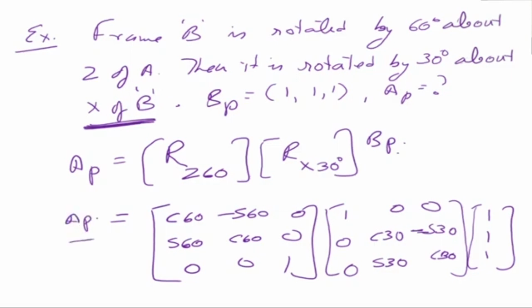So what we noted here is that we have not pre-multiplied the matrices. We keep the order of multiplication the same. The order of rotation, the order of multiplication is the same. But in robotics, we normally don't do this. But just note that this is also there. Now, we have talked about the rotation matrices, and we can have any number of rotations. If you're rotating about the fixed axis, then you just pre-multiply the matrices. So it's as simple as that. Now, we have finished our rotation matrices.